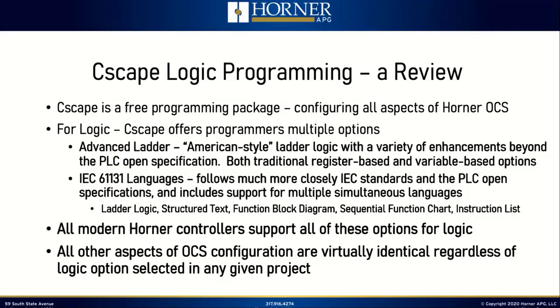Now, that being said, IEC 61131 languages have been very popular for some time, and we've been supporting them for some time. So as an alternative to just strictly using advanced ladder, you can choose instead to use IEC languages. And those, from a Horner standpoint, follow much more closely the IEC standards and the PLCopen specifications. So we didn't go off and do some interesting, unique things from an Americanization standpoint. We decided we should probably follow the specification pretty closely.